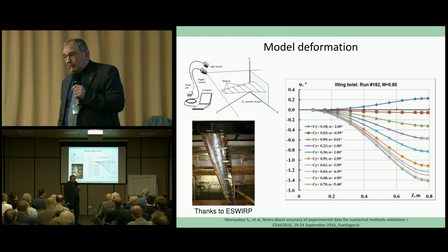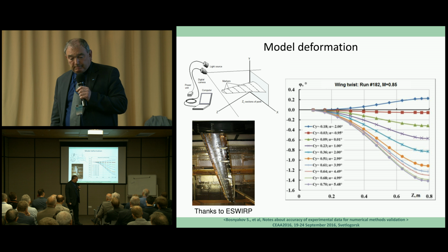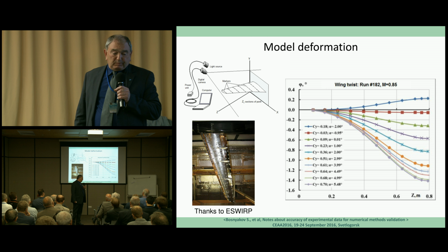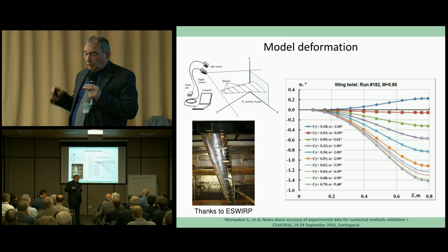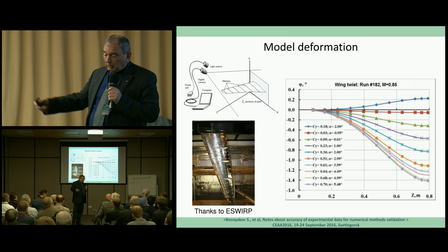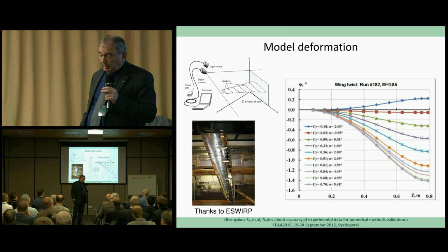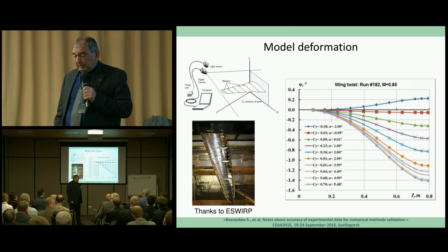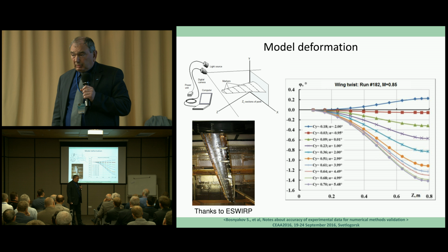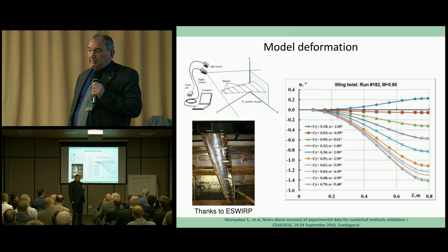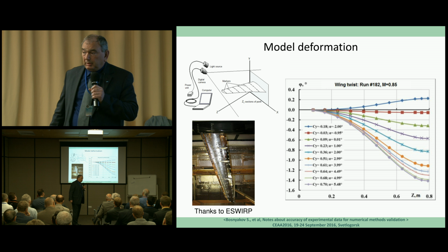Therefore, it's an absolutely necessary step to organize a so-called pre-campaign wind tunnel occupation, when the model is loaded without flow, without flux, but it's on the sting and on the support, and this campaign permits you to create real coefficients for the structural model. In this case, it's possible to calculate real deformation. It's also an official procedure now.